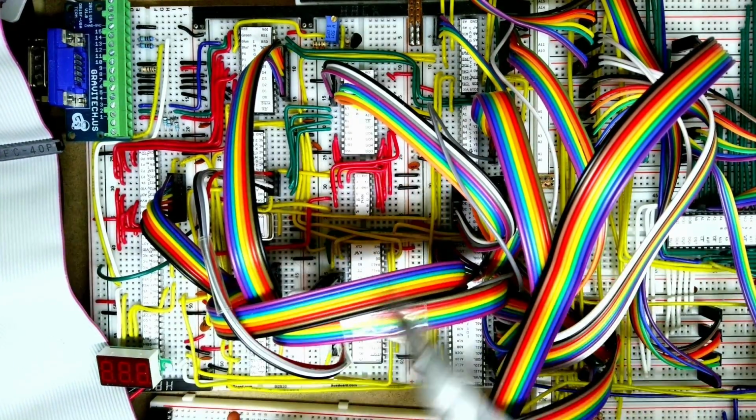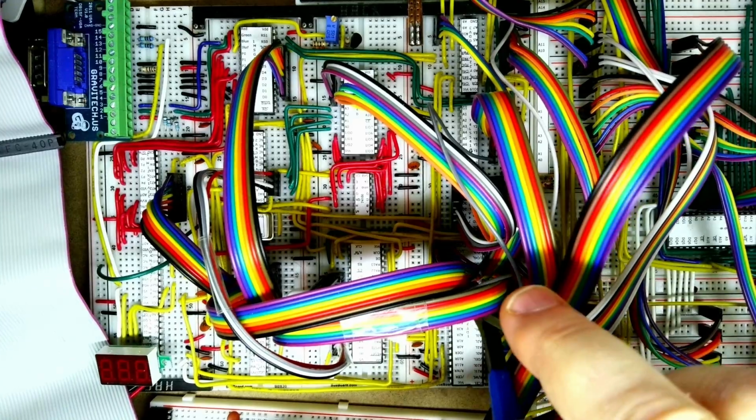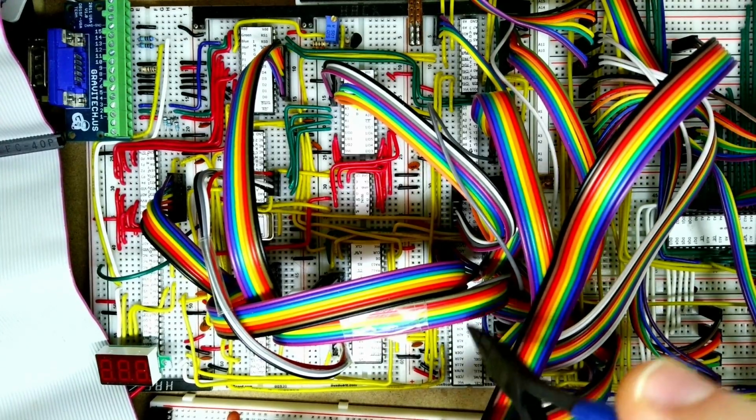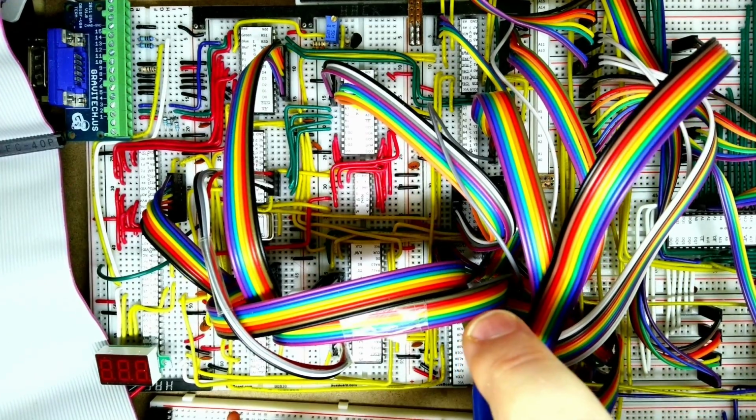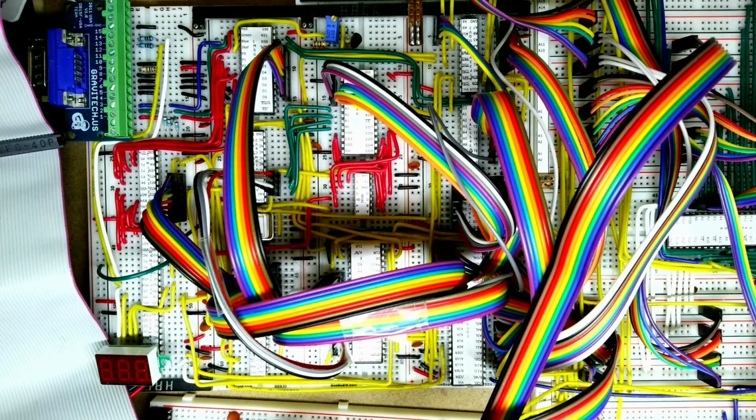I'm not going to dismantle this card. We're going to leave this card as it is. We'll be using a lot of the design elements of it on a new card. The main change is that we're going to need to include suitable multiplexing around the 32K static RAM chip I'm going to be using for the video RAM. For the moment, I'm only going to use 16K of that, but we might have some options in later videos to increase the color depth and do various other things, perhaps if we make use of more of the video RAM.